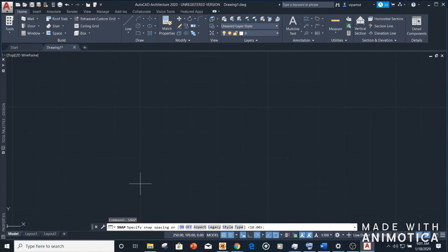So once you have that, for example, let's say we draw a line and you want the line to be 50 millimeters, you're gonna go across 5 boxes, and that's gonna be 50. So you can see 50 comes up in the circle, the cursor, which is blue, and that's 5 boxes. So you left click to complete your line, and let's say you want 30 millimeters, you're gonna go down how much? 3 boxes, right? So you go down 3 boxes, and then to complete the square, you left click all the way until you get to the start.